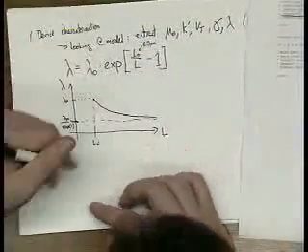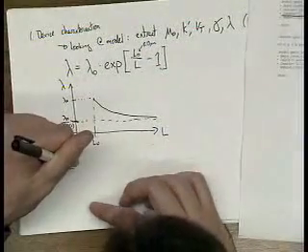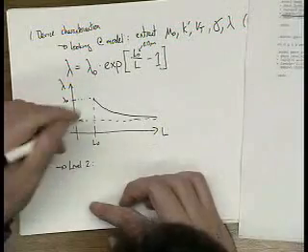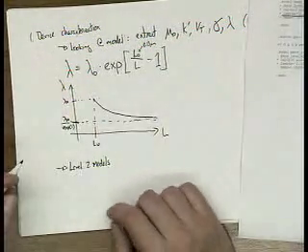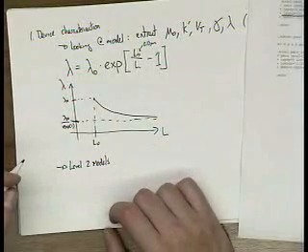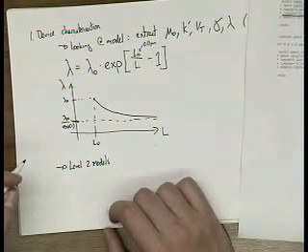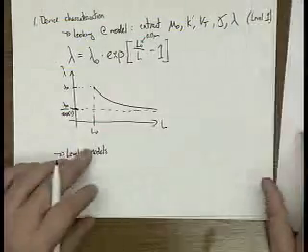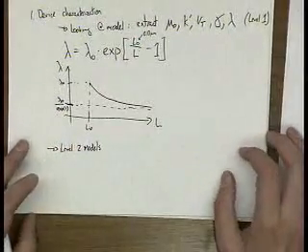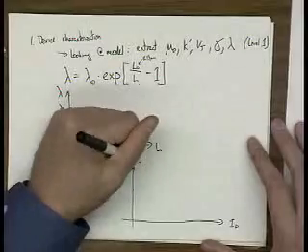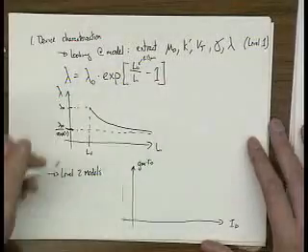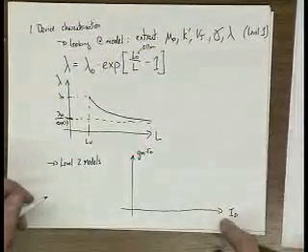Another thing to keep in mind is that the models we're giving you are actually level 2 models, not level 1. What the level 2 models are used for, and you'll remember this from homework 1, is to model subthreshold. This is something I went over in office hours a couple of weeks ago. Let's do a real quick calculation of what the gain of a transistor, gm times rout, is as a function of the device current.